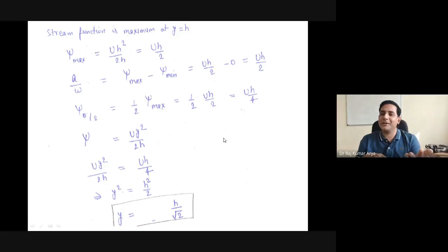You came to the right point. In earlier times also, people used to do the same, to find how fast the flood is flowing. They put one person at one end, another person somewhere far away, say 30 or 50 meters, so that they get a reasonable time. Put a leaf there, turn on your watch, and ask your friend to note the time when the leaf crosses here. That's the easiest way to calculate the velocity without any sophisticated instrument.